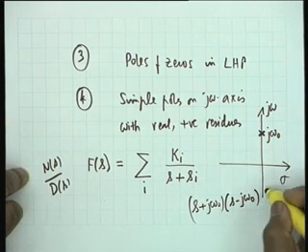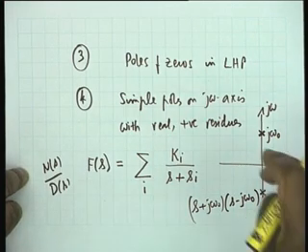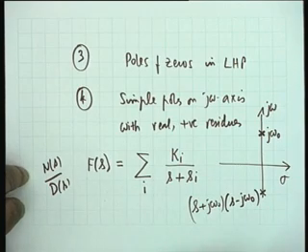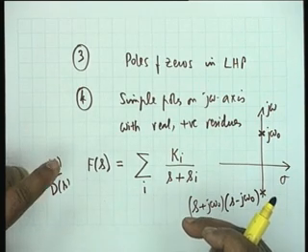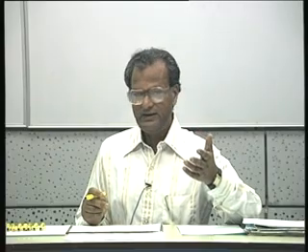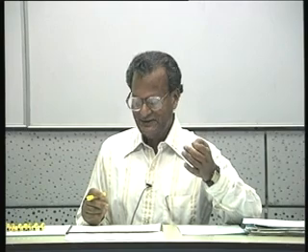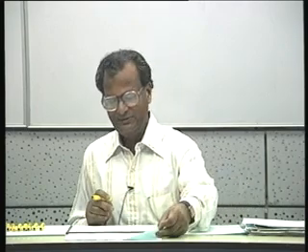And so this is one of the poles, the other pole must be here. Okay. Now if there exists a pole on the j omega axis, then this pole must be simple and the residue there must be real and positive. What is a residue, someone asked yesterday. Now I suppose that should have been done in signals and systems, but all right, we will consider this.